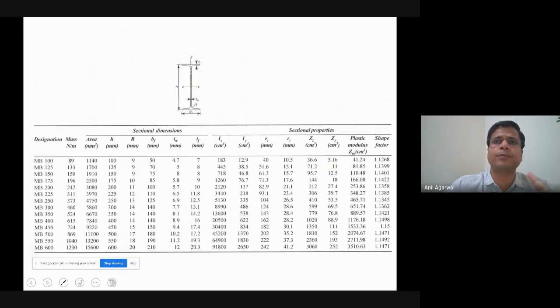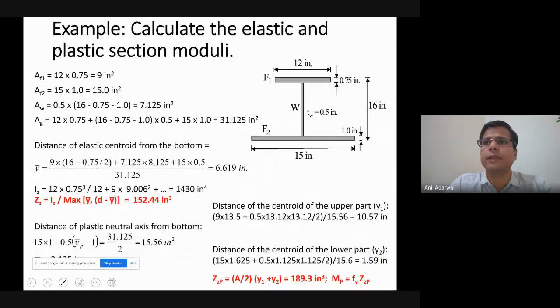Okay. So from the limit state point of view, if you think of a flexural member undergoing flexural failure, the limit state would have been yielding or plasticization. Yielding means extreme fiber yielding versus plasticization of the entire cross section. Condition two is that it should not undergo local buckling. Correct? So basically, local buckling as such is not a limit state as far as the design provisions of IS 800 are concerned.